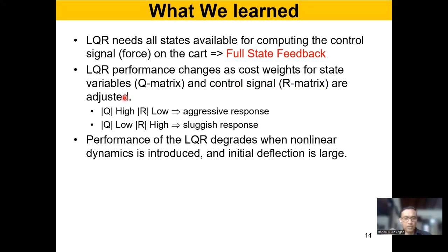So, of course, you can adjust Q and R based on a certain situation. If you can handle large errors without any major issue, then you can have Q small. And if you have your energy at a cheaper price, you can make R small.